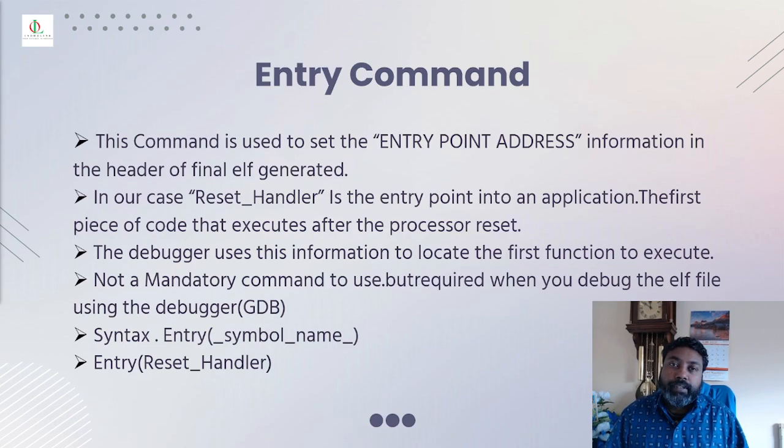So in our case, we are saying when you press the reset button on this board, the black button, it starts and lets the programmer know that the reset button is pressed. Therefore, from the entry point, it has to go to the reset handler.